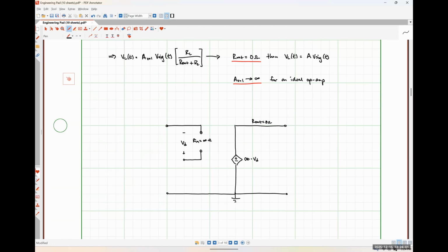And now I'm going to make my external connections. So I'm going to try to find the voltage gain of this system. So just for the sake of making things easier, once again, I'm going to apply a 1 volt source here so that we can just say V out over 1 volt is our voltage gain. Here's my 5 kilo ohm resistor connected between my inverting input terminal and ground. Here's my feedback resistor.